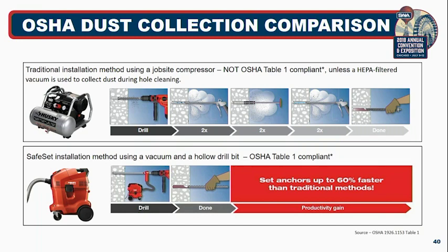There's also an additional method that you can actually use to ensure properly cleaned holes. These are becoming very popular in the market now. It's hollow drill bit systems. These are attached to vacuums where, as the holes are being drilled out, the dust gets sucked out, right? And so there's no going back and having to blow out the holes and brush them out and suck out the dust. Blow out the dust again.